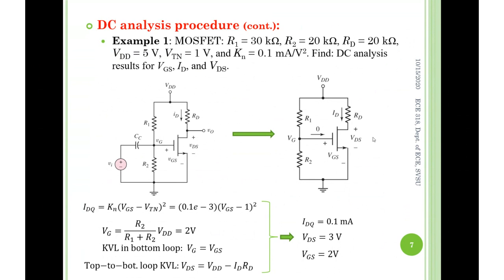You need to increase VDS really a lot to increase ID a little bit. So you won't be able to increase ID a lot and squeeze VDS back to the non-saturation region. No, that won't happen.